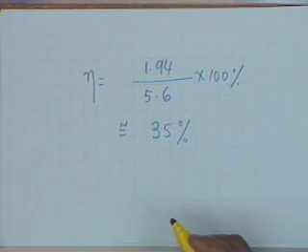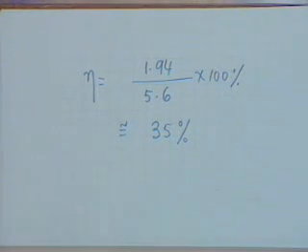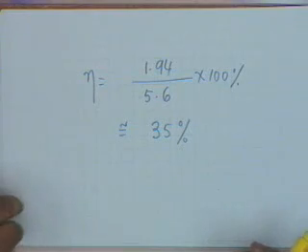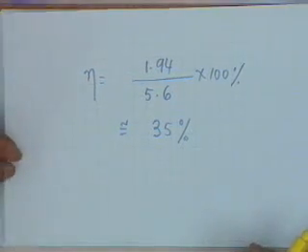The theoretical maximum is 50%, what we can achieve is approximately 35%, and this is a fact of life. The design has to be very carefully done by looking at the transistor characteristics. For power amplifiers, transistor characteristics are a must if you wish to keep the distortion to within reasonable limits. Now, if we go back to the transistor characteristics once more,